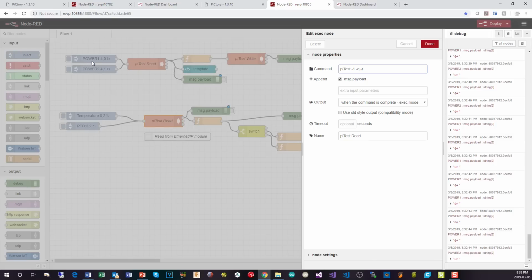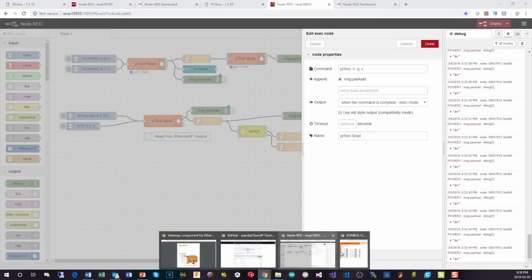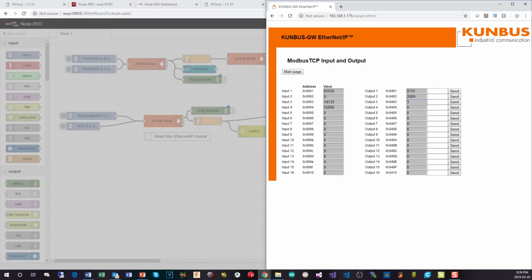Like up here, we've got power 1, power 2. Here we're using an offset. All right, so we're reading the RTD value that's being put across. And if you remember, we saw that in here. So here's the contactless IR sensor value, and sorry, this one is the RTD, and this one is the contactless infrared sensor. Now why is this one reading much higher now compared to this? I moved it and put it pointing down onto the power supply, which obviously is running a lot warmer than the ambient. Well, about 8 degrees warmer, that's all, because it's not heavily loaded.